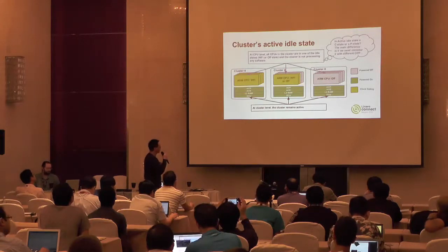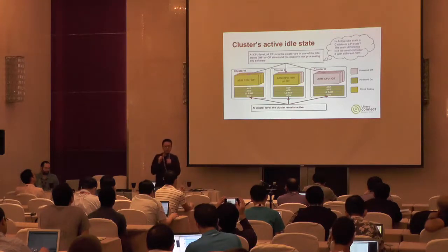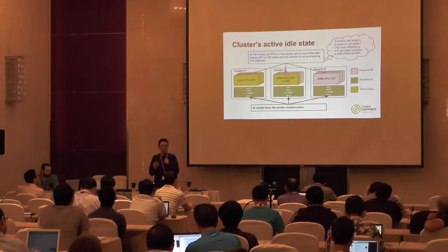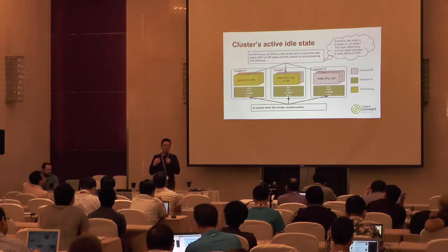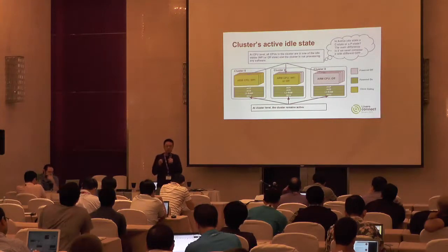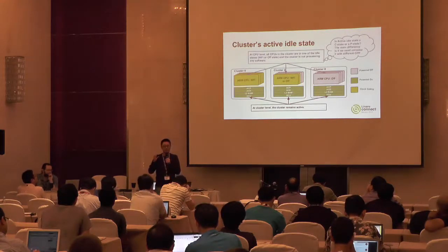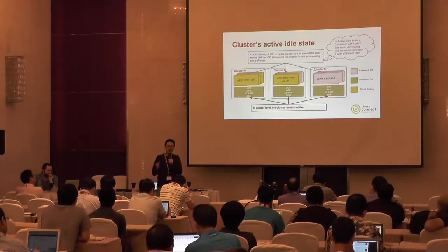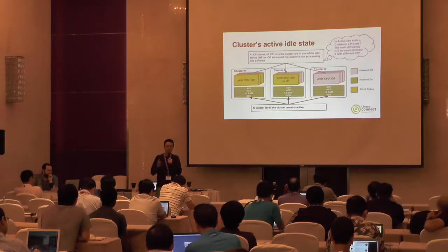The question is, there is a software behavior where we can think there are 4 CPUs in the cluster and every CPU is not working anymore. That is the software's view or perspective, but for the hardware, the CPUs can actually have different power states. Maybe the CPU has run into the WFI state, or maybe the CPU has been totally powered off.